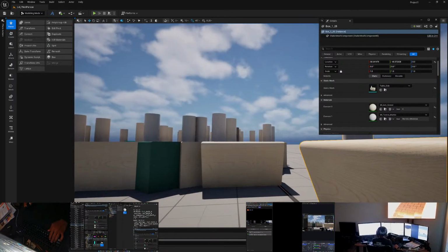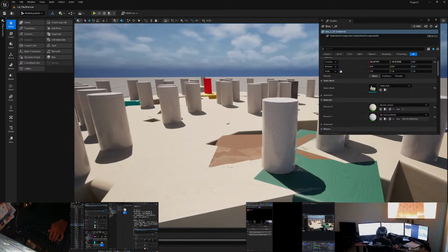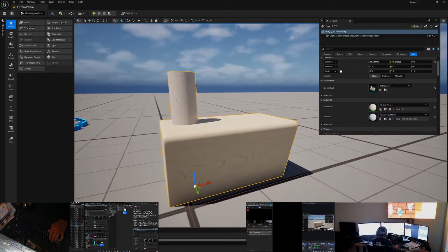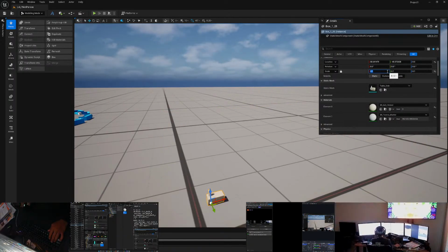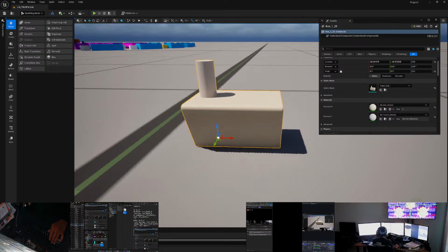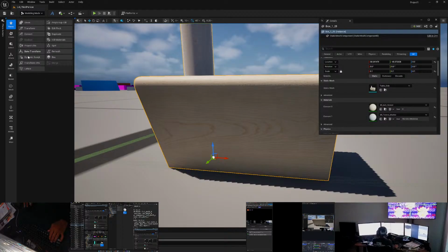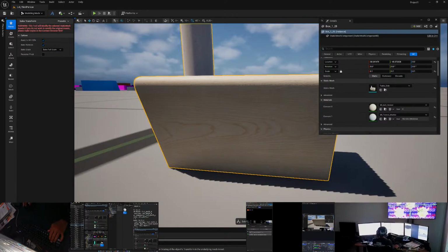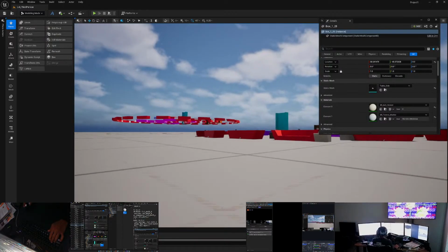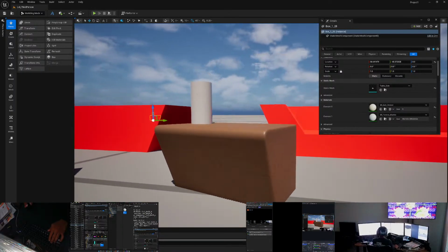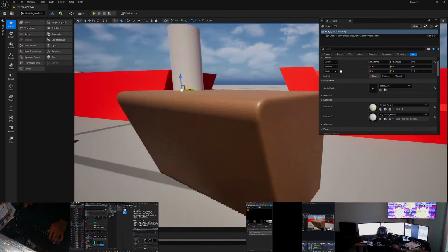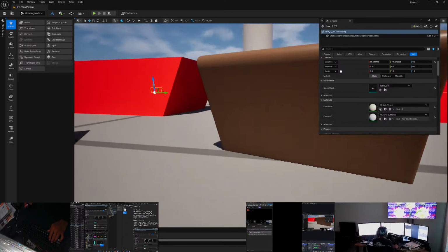Except, as you can see, all those tables look absolutely huge, but I can go back to my scale and set it to 0.1, and then bake transform and accept, and now all my tables are scaled appropriately again, but they have this nice bevel. Look at how beautiful.